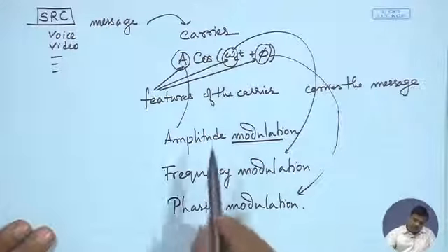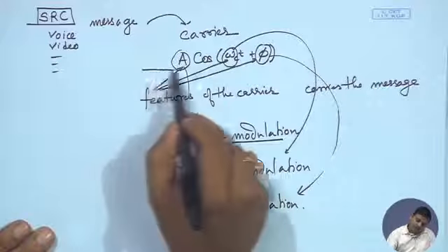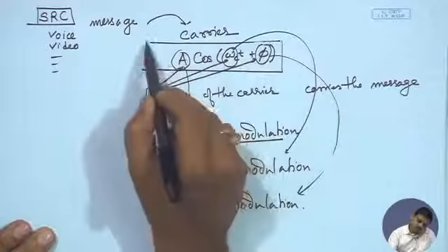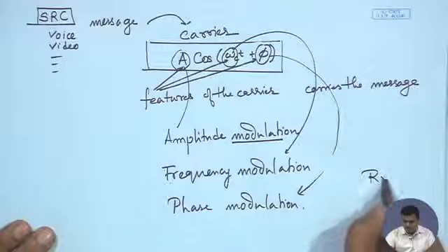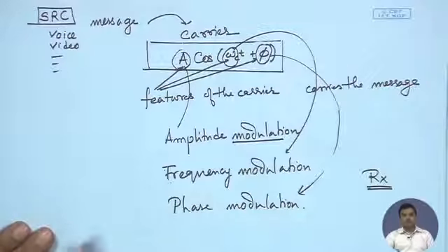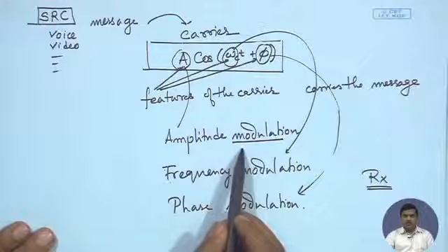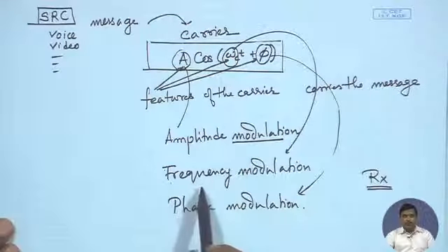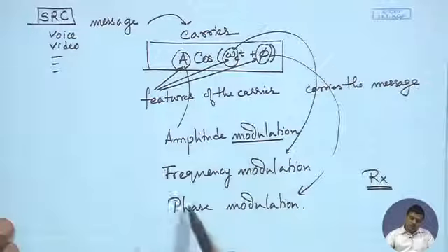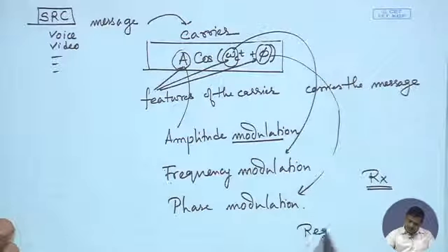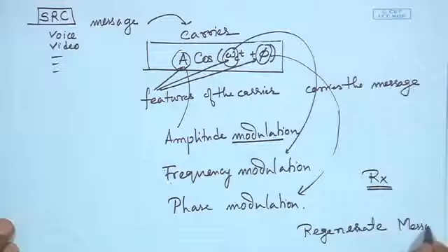While you studied different ways of changing a carrier signal to carry some message, you also studied the receivers, the different circuits by which one could demodulate an amplitude modulated signal, typically the envelope detector. Then you had the frequency discriminator for frequency modulation, and phase matching for phase demodulation. So you could demodulate the signal and regenerate the message at the receiver.